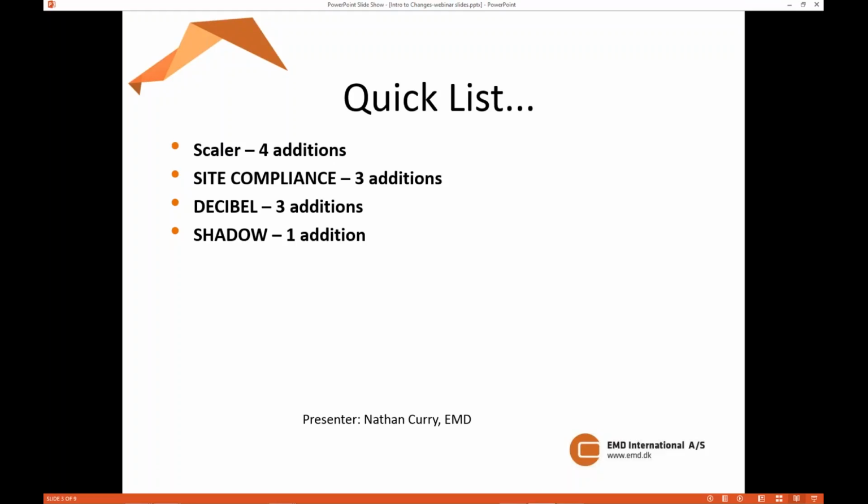So you would need to know the settings that are important for your country or for your region, but otherwise it is there to be used with some default values. Then in shadow, there's been one addition, and that's the incorporation of flicker stop or curtailment with a sort of decision table that'll make it easy for design of flicker stop strategy.